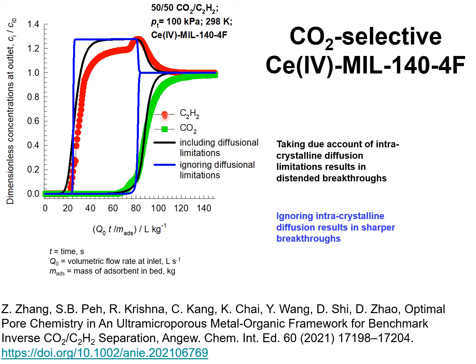The message we draw from this comparison is that for a realistic prediction of productivities of desired products in transient breakthroughs and fixed bed adsorbers, we need to consider intracrystalline diffusion limitations.